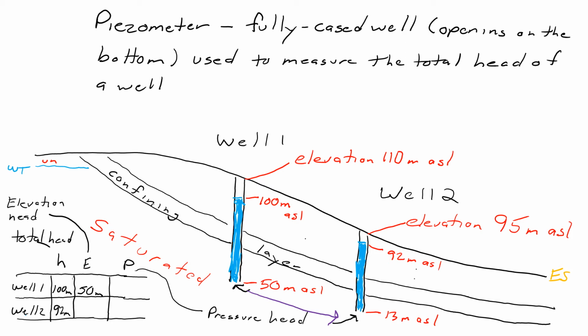I just said that really wrong. It's been a long day. Let me start that over, okay? I just gave you a great definition for pressure head, okay? You guys just gave me the pressure head. So pressure head is how high pressure is pushing water up into your piezometer. As it turns out, it is actually 50 meters, like you said. Okay, so I'm just going to move that over to the pressure and get rid of this.